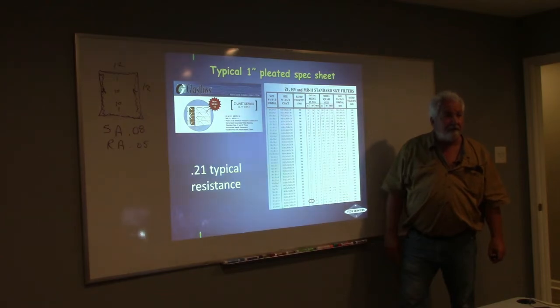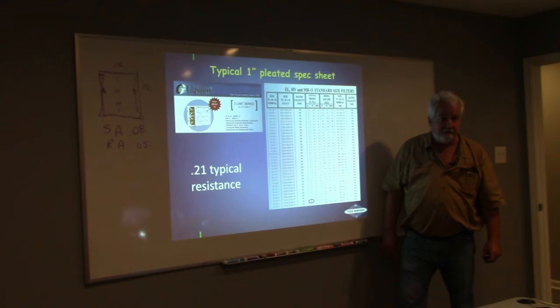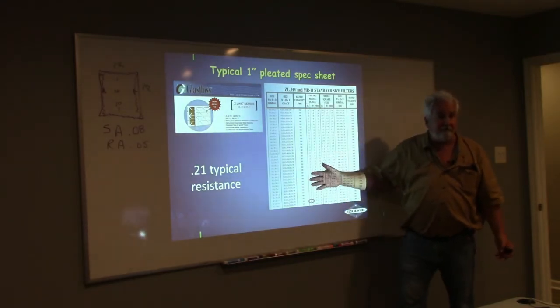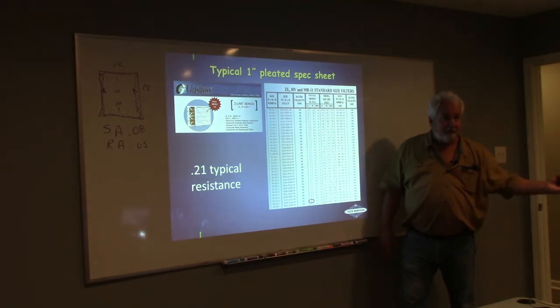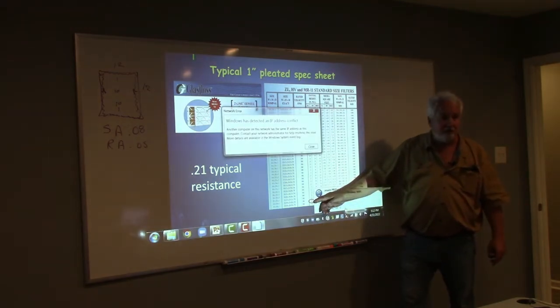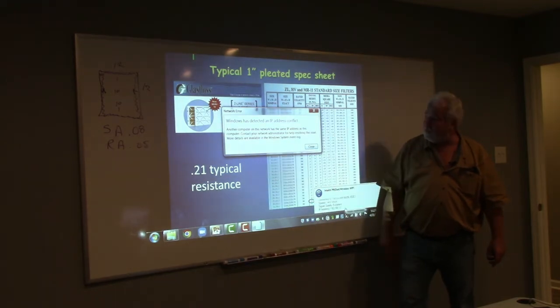So let's just say that you're at a 0.7. If you just change out the filter from a pleated filter to a poly filter, we've already dropped 0.1 off of that. Doesn't that make sense? So now I'm back into that 0.6 where it's working.